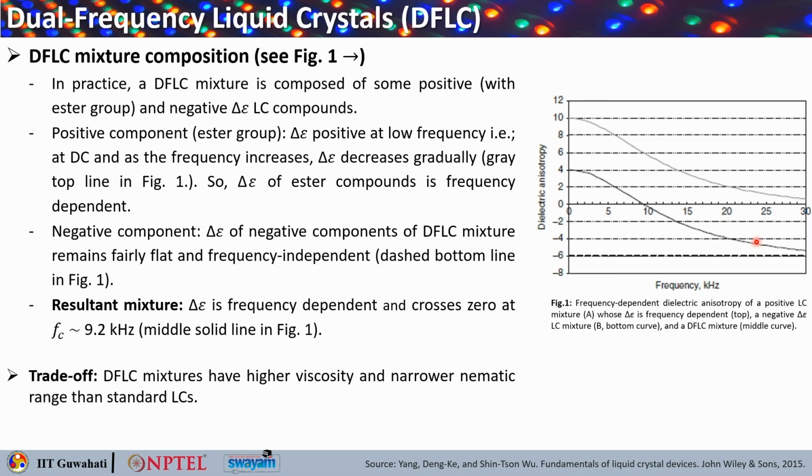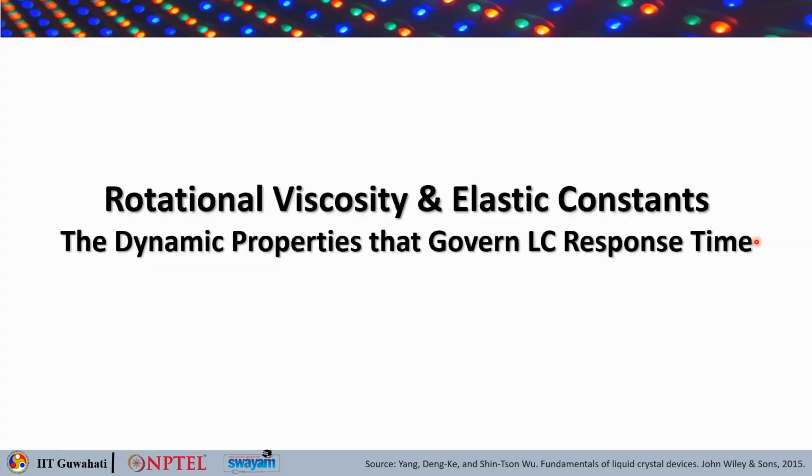So, what is the trade-off here? These DFLC mixtures have a higher viscosity and narrower nematic range as compared to the standard liquid crystals. Now, we will discuss the rotational viscosity and the elastic constants. These are the dynamic properties that govern the liquid crystal response time.